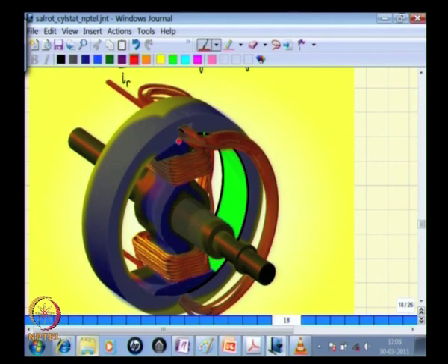Because the entire air gap that is faced by this flux lies here and here, that is, this pole face to stator is one air gap, this pole face to stator is another air gap, and irrespective of where the rotor is, that air gap is going to remain the same, which means that the rotor MMF that is so generated faces a constant air gap irrespective of rotation.